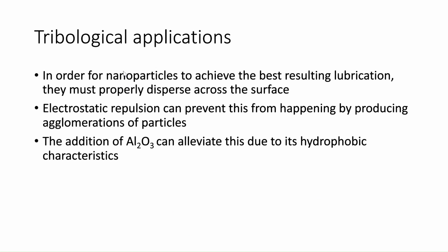And one of the problems that stands in the way of this lubrication is that sometimes the particles aren't actually able to properly disperse themselves across the surface. And this is most of the time due to this electrostatic repulsion that can lead to particles sort of clumping up together. So to combat this, the addition of aluminum oxide can actually alleviate this due to its hydrophobic characteristics.